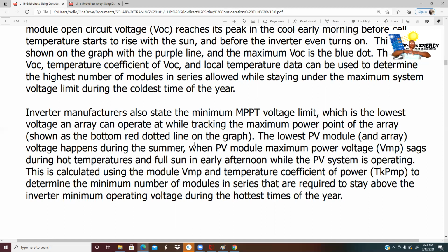This is very important. When you are building a system, the inverter is very important. The inverter's job is to change the DC current that comes from your PV module into AC current, as we said in the early lessons. But there are a lot of factors that affect the full operation of an inverter. Power factors are very important, and as a designer, you have to take these into consideration. If not, you're going to damage an inverter that costs hundreds, if not thousands of dollars.